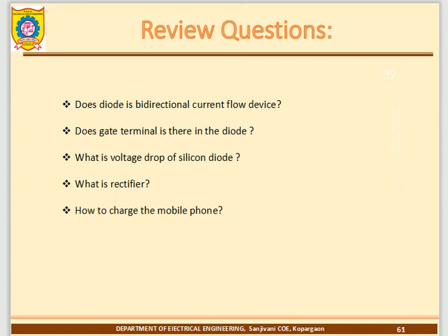After that the 10 volt AC is rectified into 10 volt DC, and the DC is filtered, followed by a voltage regulator. For example, a 7805 regulator gives a constant 5 volt. LM317 can be used to fix the 3.5 volt. That's all.